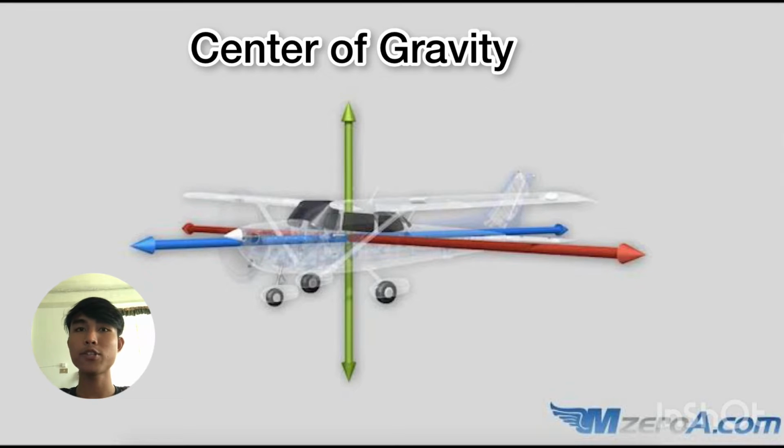You might be curious about CG, what I'm talking about. The CG of a body is the theoretical point at which the entire weight of the body is assumed to be concentrated. It is the point at which the aircraft will balance. It is what the aircraft moves around.